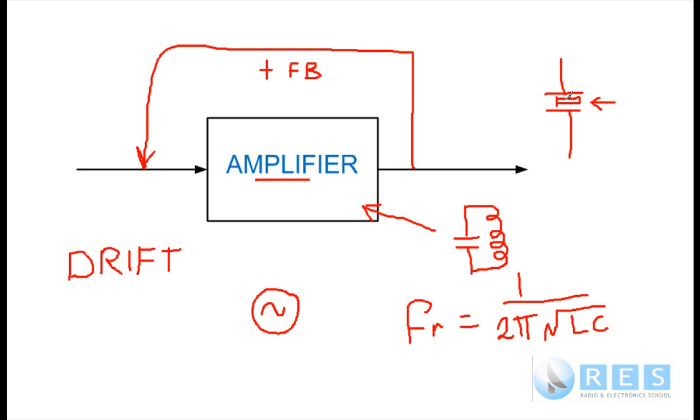Quartz is a piezoelectric material. What that means is if we put a voltage on a piece of quartz, it will twist. And if we remove that voltage, then the crystal will vibrate at radio frequencies for a little while. And it will vibrate or oscillate much longer than an LC circuit. Remember we talked about Q? If we made this LC circuit oscillate, we would get a damped oscillation. The reason we get that damped oscillation is because of the losses in this circuit. It has low Q.